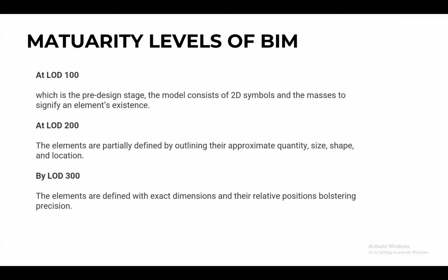Then if you have an LOD 300 model, it's similar to SD, schematic design 100 drawings. You can find dimensions and define all the elements, so you can extract quantities based on those elements under this LOD 300. It is a developed model.